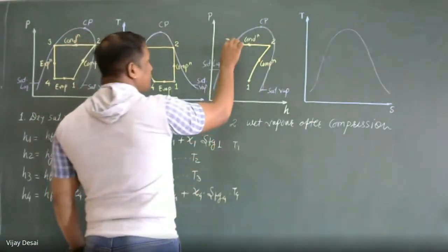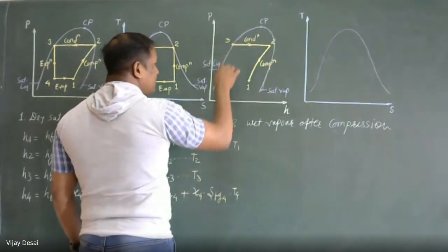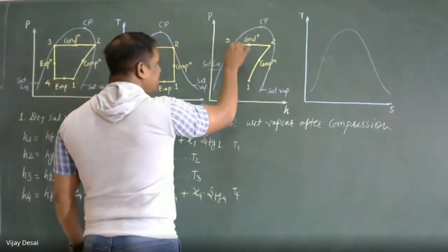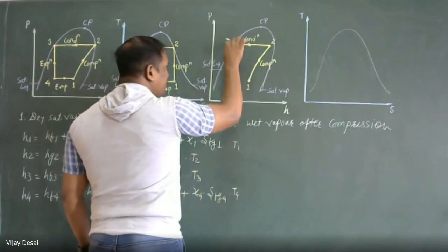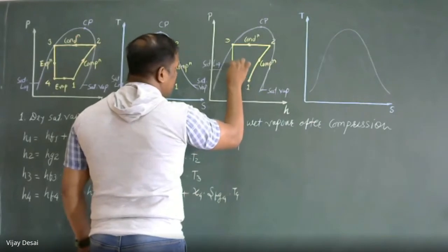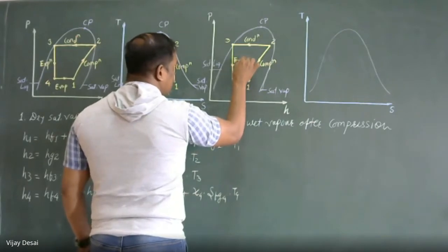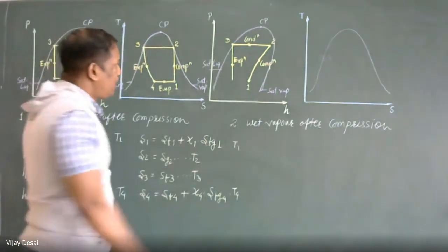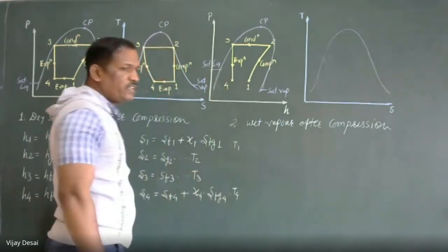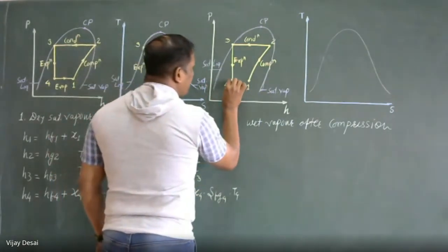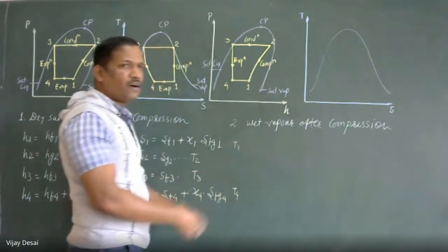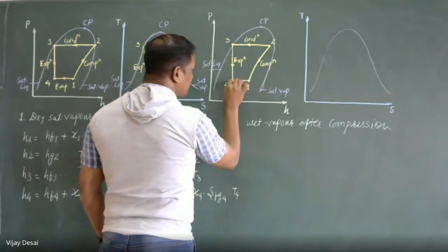So after the condenser, we observe that our refrigerant becomes saturated liquid. Then we supply this refrigerant into the throttling device, where the throttling process is a constant enthalpy process. So an exact vertical line, this is the expansion process, a constant enthalpy line. After this throttling process, we supply the refrigerant to the evaporator unit, where it absorbs latent heat, so its dryness fraction improves.